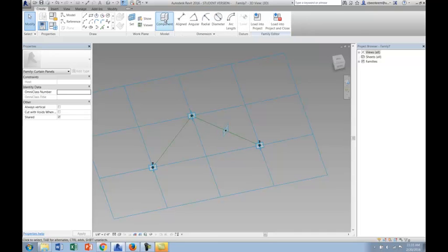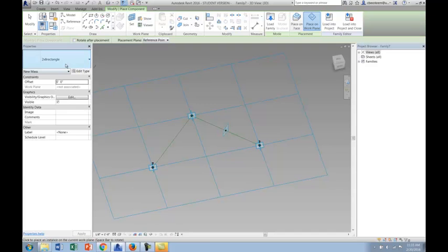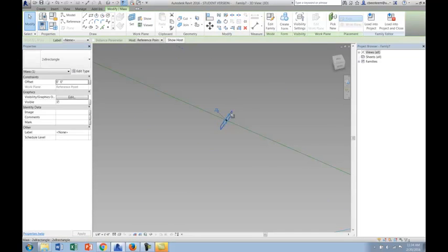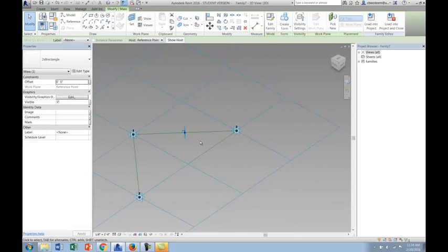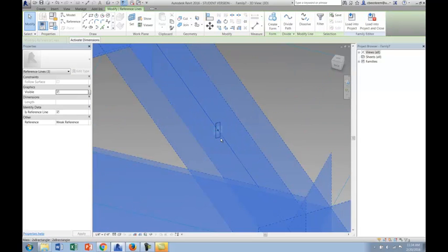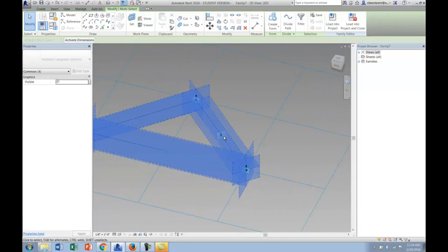And now under create, I'm going to go to create and component. And you can see by default that actually brought in my 2 by 8 rectangle. And it'll snap right to that point or to the plane. And actually the plane is what we want to make sure and reference it to, because then we're going to need to rotate it. I'm going to use the snaps here to rotate it 90 degrees so it's sitting like a mullion would along this rectangle.